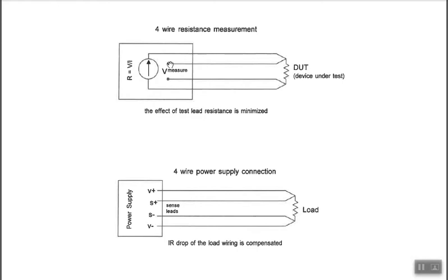So you've got your voltage measurement inside your ohm meter that can just have a look at the voltage way out here and not include any kind of voltage drop on the wires. So you're going to have a 4-wire resistance measurement is what they would call it. And you can buy special test leads that don't look any different here. It just looks like a single lead, but there are 2 wires inside it. And at the point of the probe, it doesn't look any different. There's just 1 probe tip.